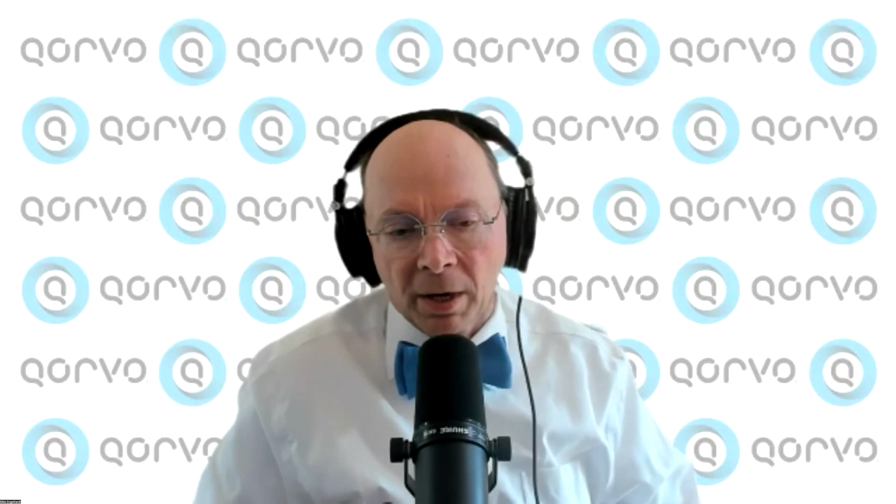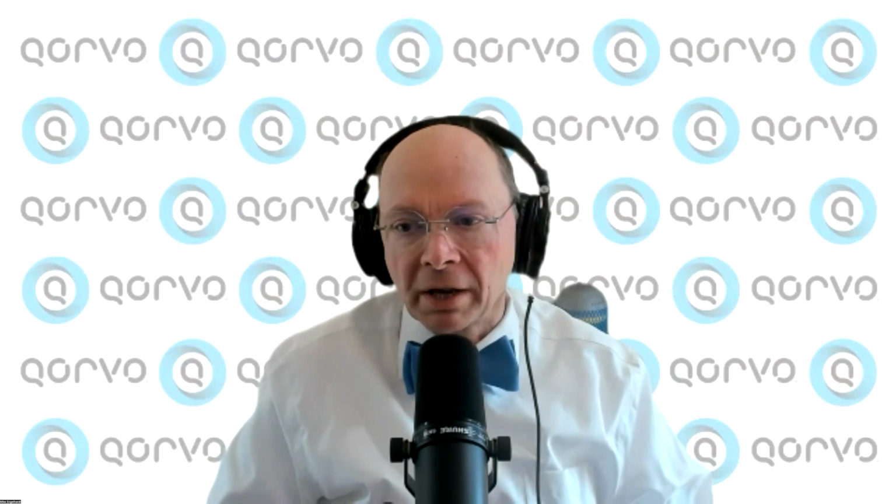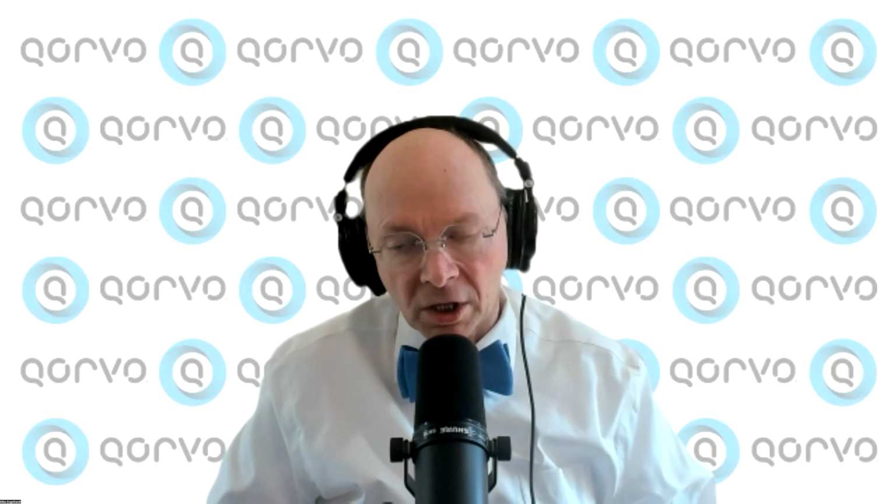Yeah, I had a problem with that. I did a JFET preamplifier one time, and I couldn't simulate the shot noise and whatever other noise was coming from the JFETs. So I was digging into data sheets trying to figure out which JFETs I should use, and it was mostly a lot of trial and error. Well, the QSpice JFET model generator should give you a pretty good handle on the noise of a JFET, because it will take care of the gross error.